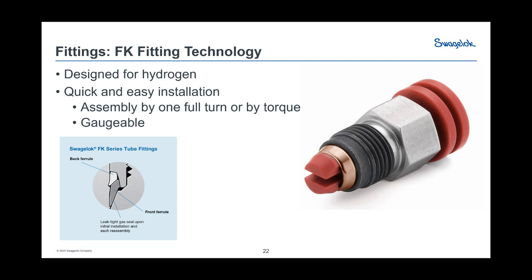Traditionally, when you get people putting together tube fittings, many of the installers, the first thing they do is take them apart, which is kind of concerning for us because we spend a lot of time and money to make sure that everything is in the right orientation and in the right part every time. And any tube fitting from Swagelok you can take out of the box, stick in a piece of tubing, and mark that tubing for depth, put the tubing in, pull it up the appropriate amount of turns, and you're done. That's it. Because we already know everything is there and in the right order. And we do that through a variety of controls within our factories.